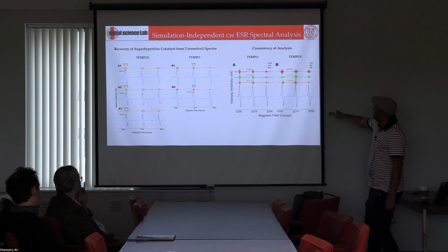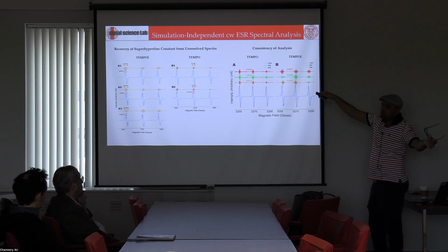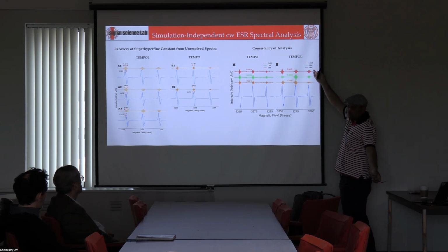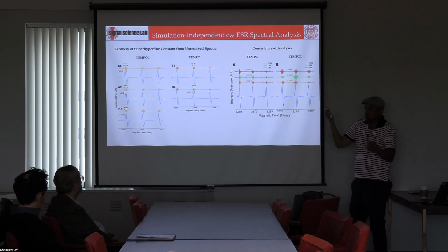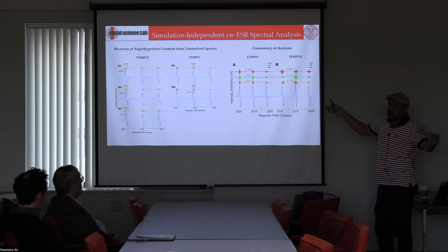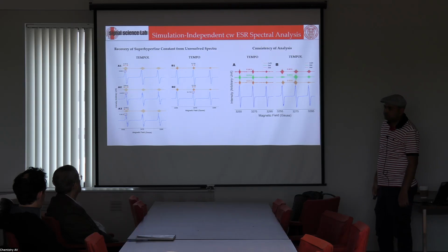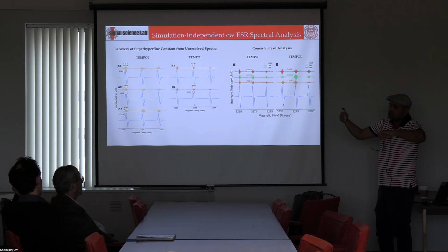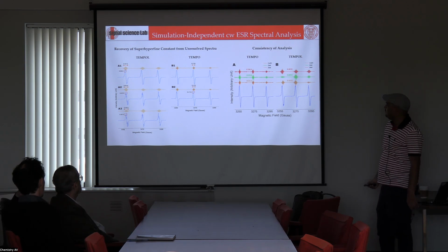And what this 6 and 9 means is the number of coefficients in a wavelet. If you have few coefficients, your resolution is sort of affected. If you have 6, you get a perfect sort of wavelet transform. If you go to 9, you overdo it. But sometimes, depending on how big the data length is, that chooses what your wavelet is. So it's like a filter length in that aspect. The bigger the filter length, the better the resolution, but it starts giving a poorer result after a certain length.